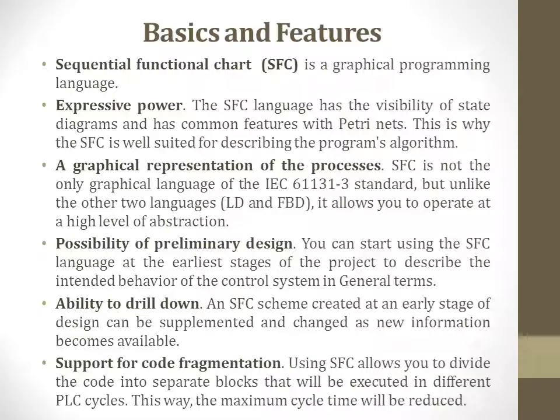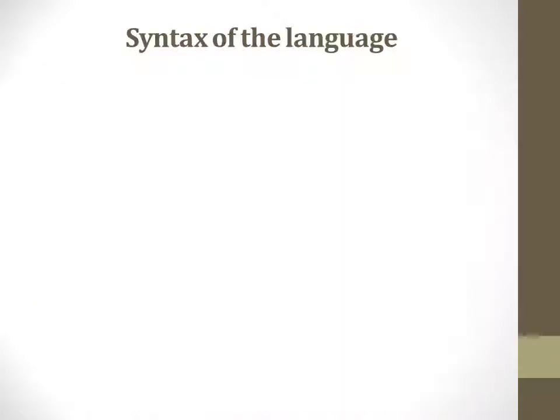The next feature is support for code fragmentation. Using SFC allows you to divide the code into separate blocks that will be executed in different PLC cycles. This way, the maximum cycle time will be reduced. So, we discussed the basics and features of this language, and we are continuing.